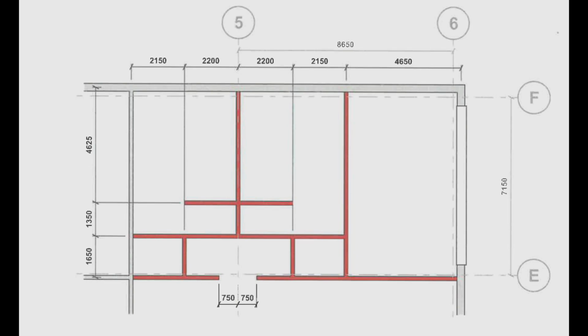In many real-world projects, you'll receive a Revit architecture or Revit structure model as the base for your MEP work. When that happens, the fixtures, fittings, and building elements you need are already in place and fully compatible with your project. But in other cases, the information provided might be only in 2D or in a non-Revit format, or in some situations, not provided at all. When that happens, it's important to understand how to model the basic building elements yourself so that the MEP services have the proper architectural and structural context.